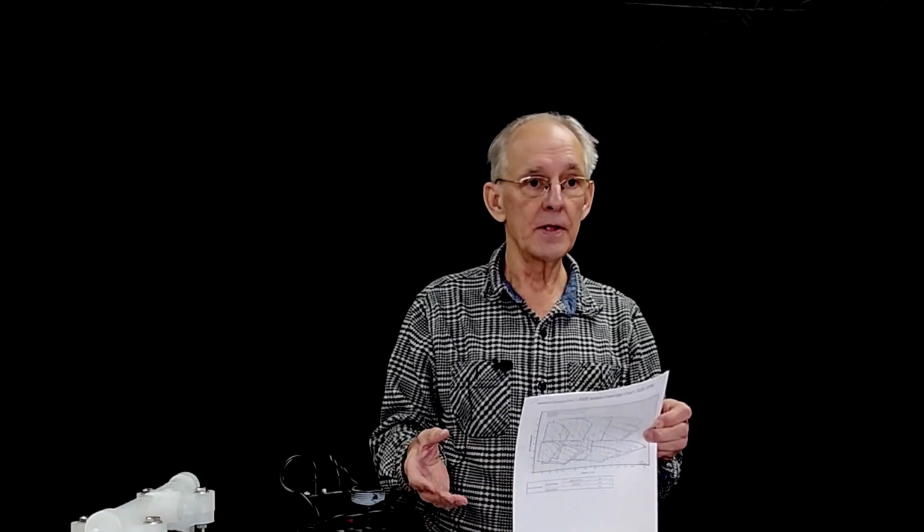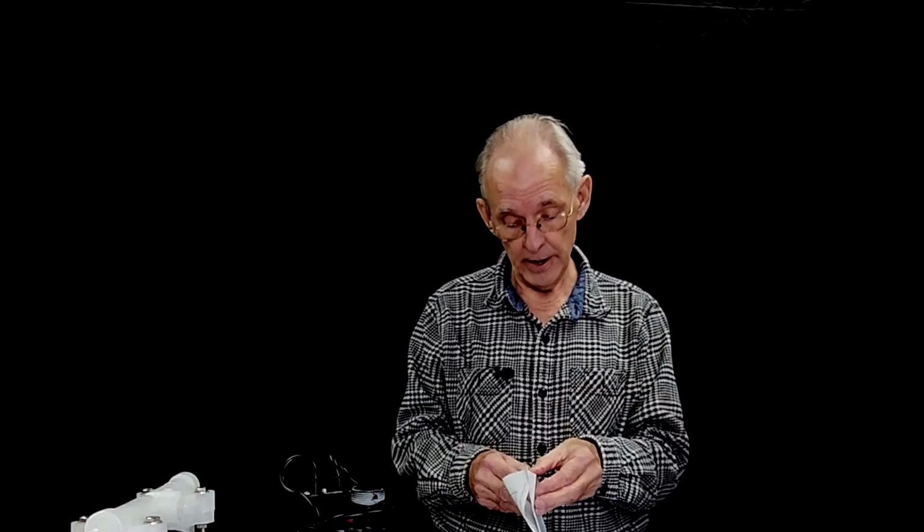And then you combine it with a rotor that goes inside, and by changing the size of the rotor, you change the characteristics of the pump. It also means that you can even tune the pump to a specific use by trimming the rotor. You buy a rotor that's a little bigger than you want, and then you trim the rotor to give you either better efficiency or a closer match to the flow with a fixed speed motor. This is a pretty typical looking pump curve.